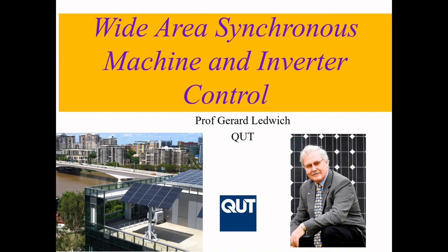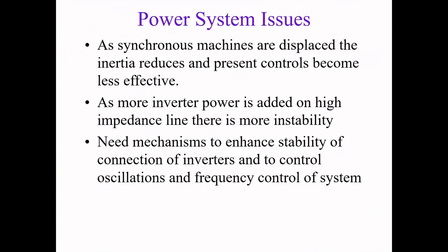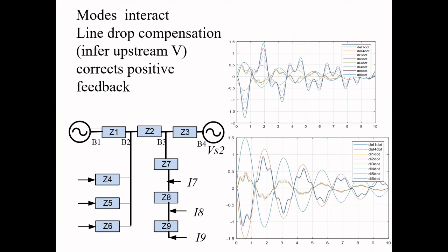My experience on the cases that I've studied to date has been of quite a high degree of robustness. When we were designing our controllers for inverter number 9 here, it knew nothing about inverters 7 and 8. And you might say, well, that's unfortunate, we'd be a lot better off if we did. And the answer is the Kalman filter can still infer a much more stable voltage than we can from its terminals. So even if we took the voltage at this point and projected it 2/3 of the way up, our interactions, our sensitivities are much reduced compared with just working to the terminal volts.